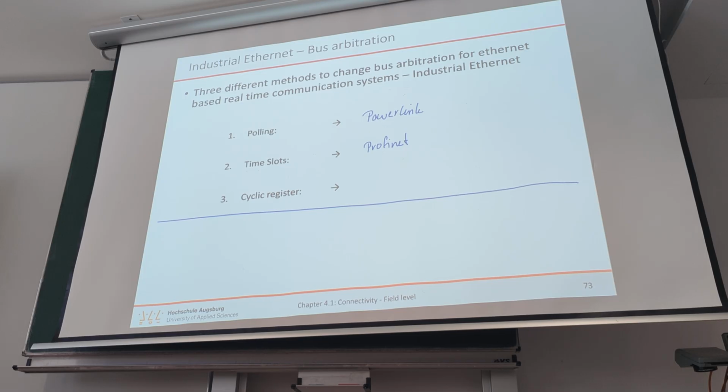When the input is sampled, all the inputs read in their values and transfer the current value in their time slot back to the PLC. And the outputs have an exact point in time where the output becomes valid.